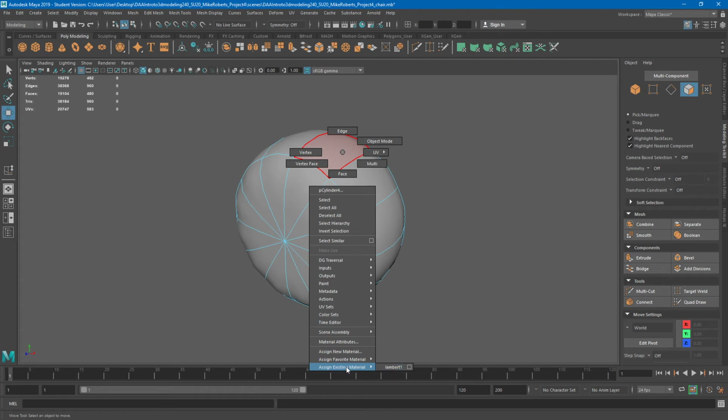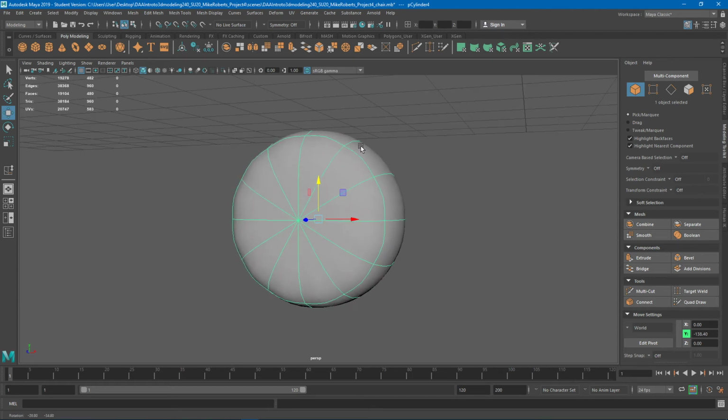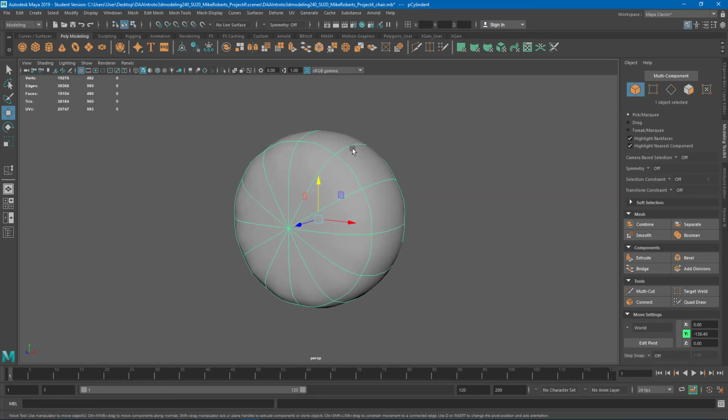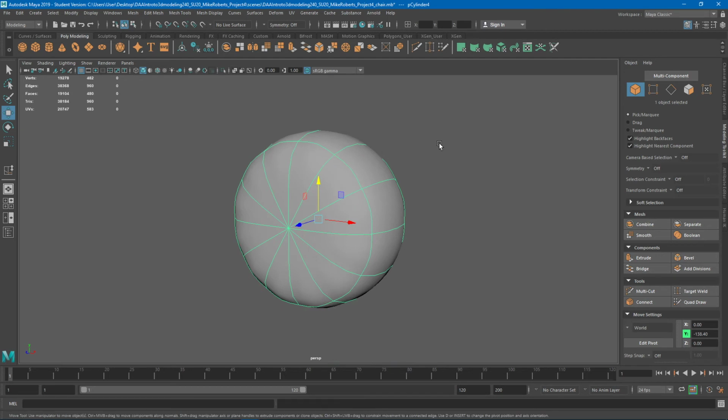So all you have to do to fix that usually, particularly if it's the bright green, is just go to the very bottom, assign existing material Lambert 1, all right? If it's kind of a wireframe, usually that'll fix it. Sometimes you might have done something way weird, but oftentimes, particularly if it's just wireframe on some polygons and not all, it's kind of a similar problem, and you used to have to reassign the material. That's kind of on everything. So kind of a quick little side talk, because a couple of you guys have had that problem recently, and I've told you it's one of those things I can explain over a message. We don't have to do a conference for it. I figure it doesn't hurt to have a video where you can see, hey, right there, boom, and it just reapplies that.